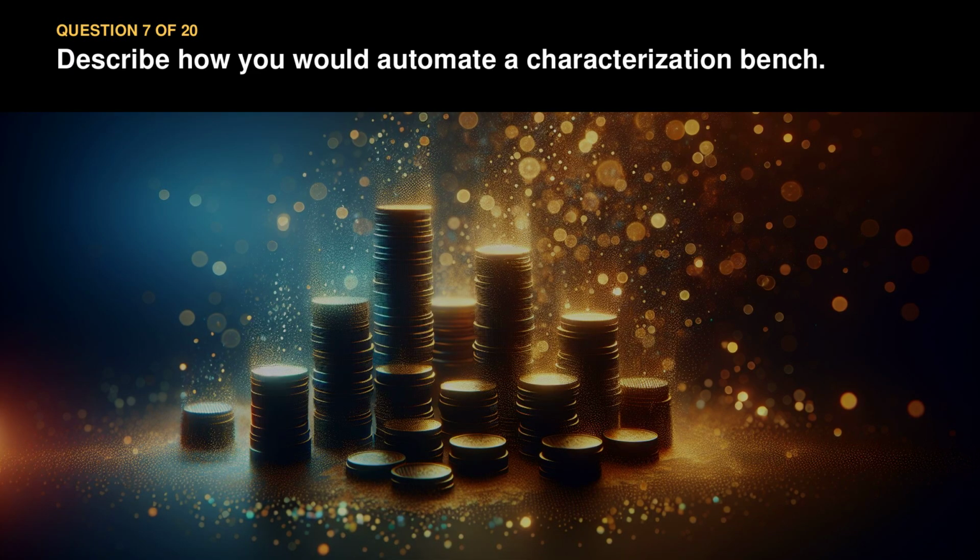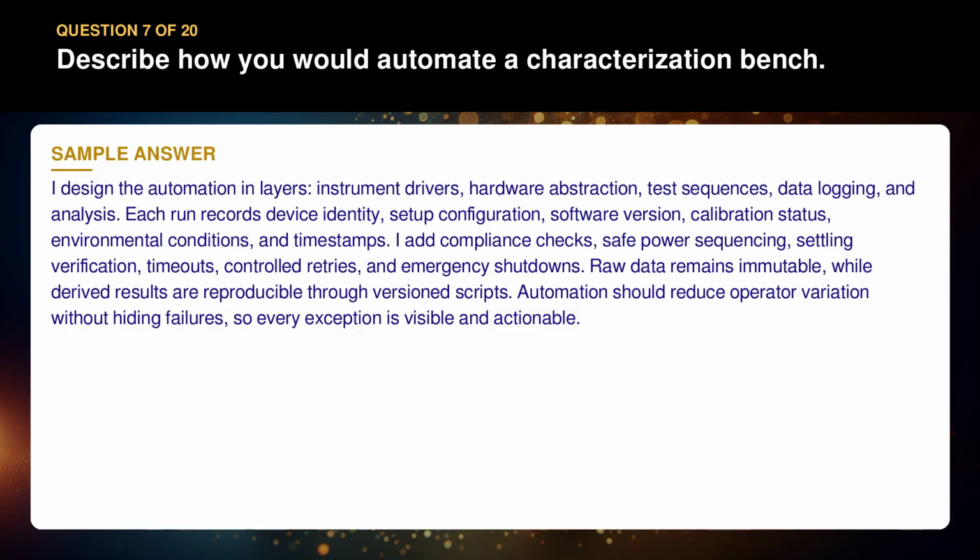Question 7. Describe how you would automate a characterization bench. I design the automation in layers: instrument drivers, hardware abstraction, test sequences, data logging, and analysis. Each run records device identity, setup configuration, software version, calibration status, environmental conditions, and timestamps. I add compliance checks, safe power sequencing, settling verification, timeouts, controlled retries, and emergency shutdowns.